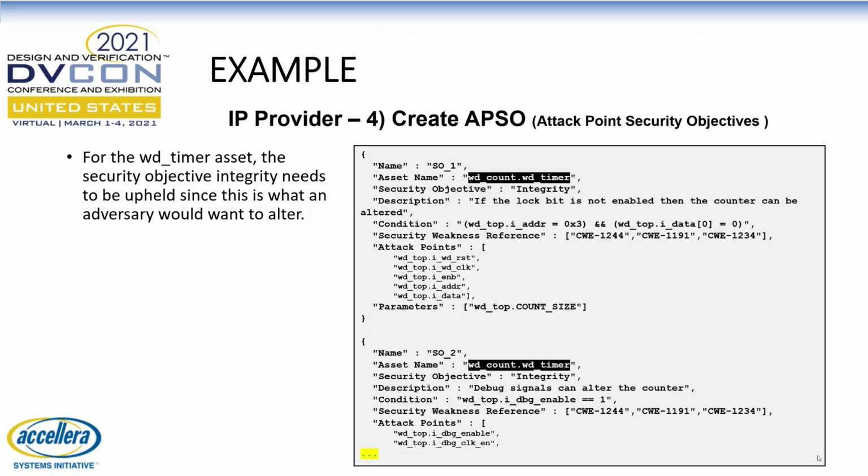So to create the APSO data objects for the timer asset, the security objective is integrity. It needs to be upheld, since this is what an adversary would want to alter. One may argue that confidentiality is also applicable, since knowing the timer's count does allow the adversary to know when the timeout could happen, and therefore, mount an attack in a timely manner. However, without preventing a timeout, the attack does not get mounted and will be undone when the timeout occurs. So therefore, the confidentiality objective does not really improve the security of the design.